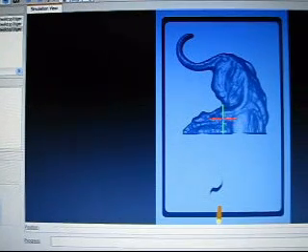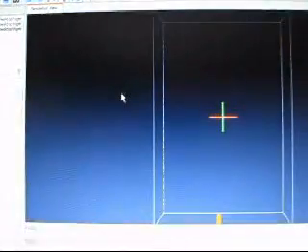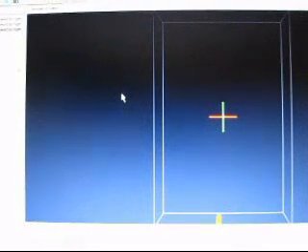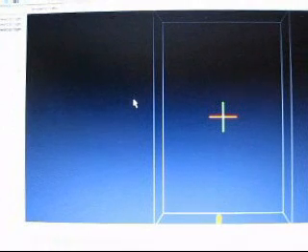So you don't divide that number by 2 like you did with your X and your Y. This thing is going to get a little confusing on you, but if you play around with it enough, you'll figure it out. I wanted the manual dimensions to be as it's actually going to be. So I'll regenerate the toolpath just for you right now so you can see what I'm talking about. Keep in mind that the Z is not going to be accurate, because it's probably going to be a little bit more than that.